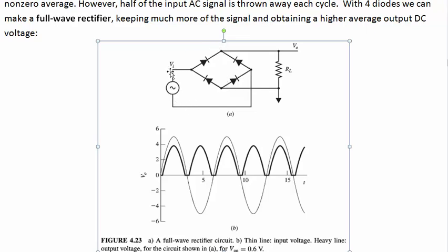So if this is a positive voltage, then what happens? Current tries to go this way. Can it go that way? Nope, gets stopped by the diode, goes up through there, drops across one diode. Then can it go there? Nope, so it appears there. So the positive voltage appears there. The negative side of it tries to go up this way. And then the negative voltage, can it go this way? No, because it's a negative. So it's trying to draw current. So it can actually go backwards through a diode and appears there.